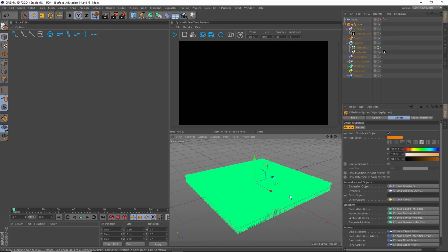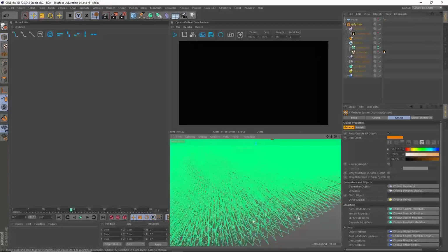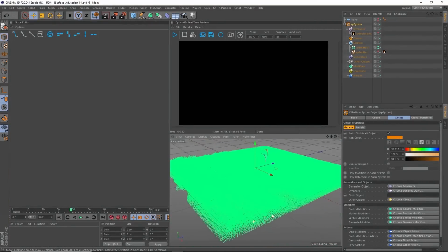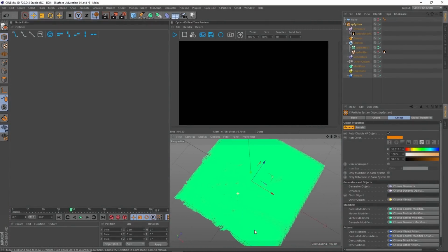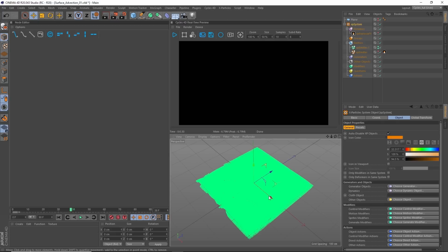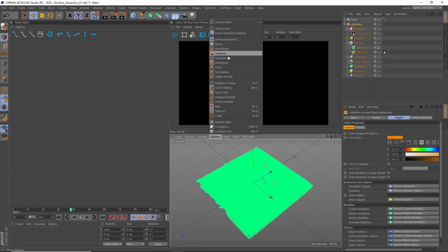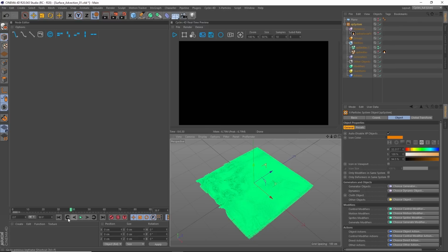Now, it's quite difficult to see how our simulation is working at the moment because we've got this display mode, these arrows that are only outlines, and they all kind of merge into one big blob, and we can't see any individual patterns developing as they rotate. A really quick trick to sort that out: if we go to the viewport options, to the OpenGL options, and just activate the ambient occlusion, we'll get this fake shadowing, and now we can see the movement a little bit better.